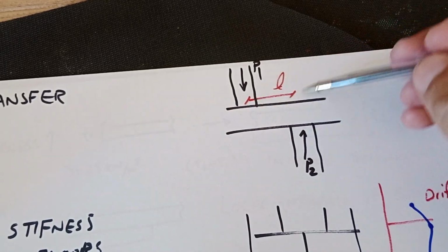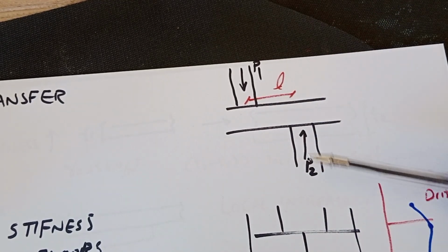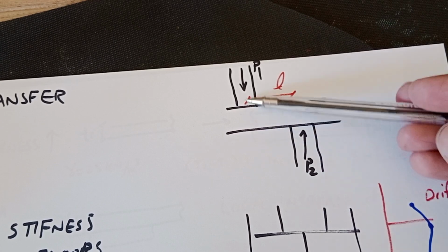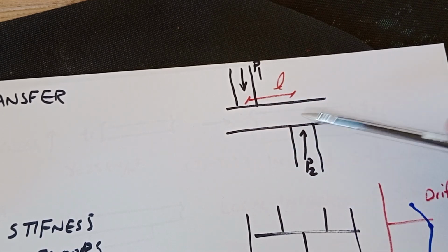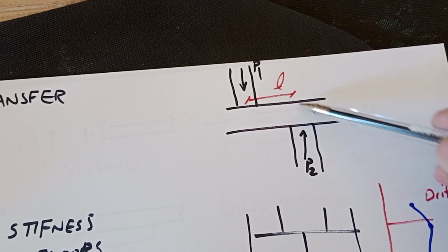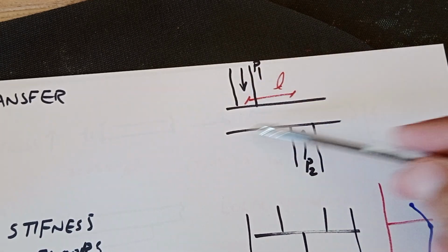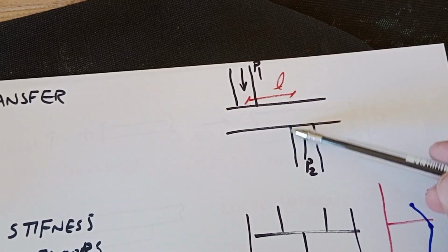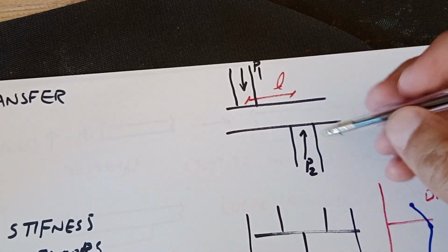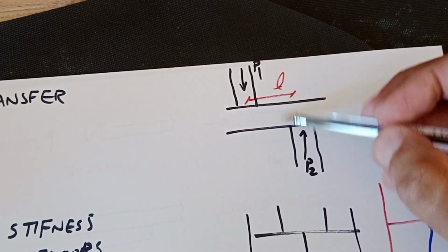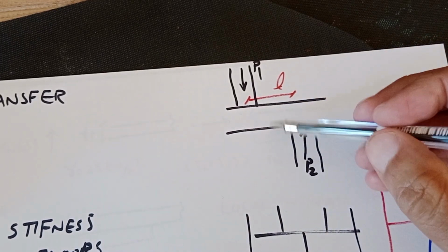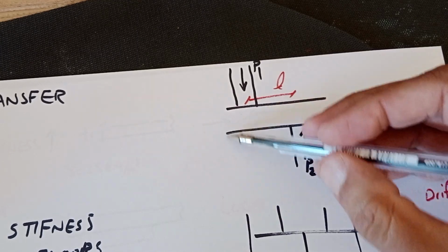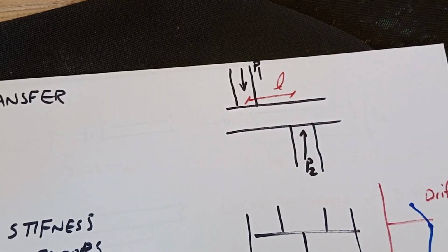Anyway, if the distance between the upper and lower column is small, I say if it's under 1 meter, definitely go and check for transfer shear in this area, because we have big loads over a short distance to be transferred, and it is definitely a shear issue. We may need some shear studs here, or we may need to increase the slab thickness, even locally around this area.